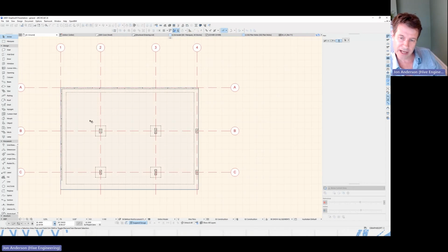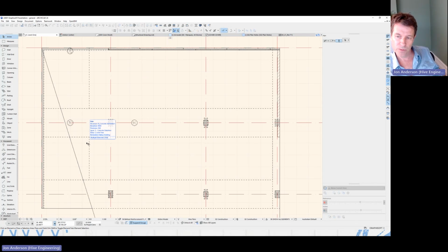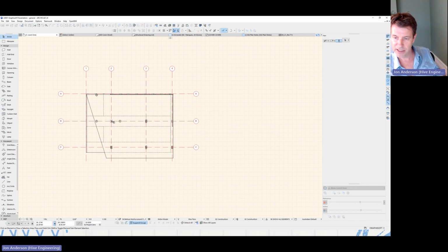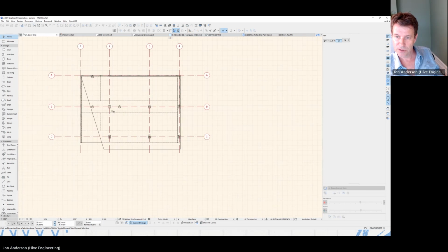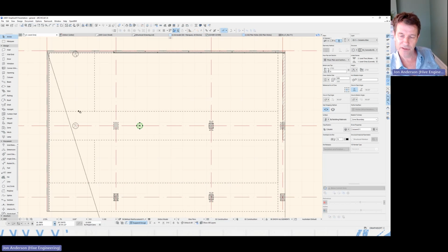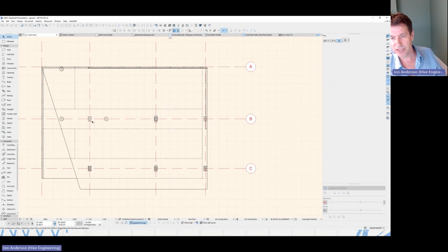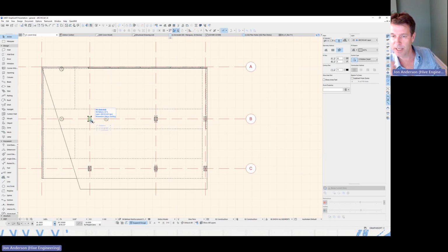And I would represent that using the slab tool mainly, and the column tool and the wall tool to generate something like that. But we very much care about what's underneath rather than just what's on top. So we have dotted elements showing columns under and solid elements showing columns over. So you can read that, you might have a column over and a column under coinciding, something like that. Unfortunately, I have to use fills for the column under because to get that to present properly.